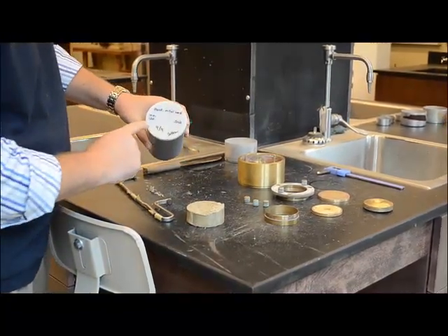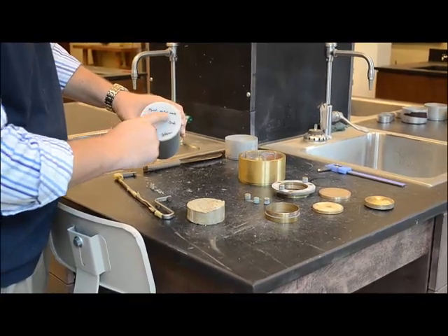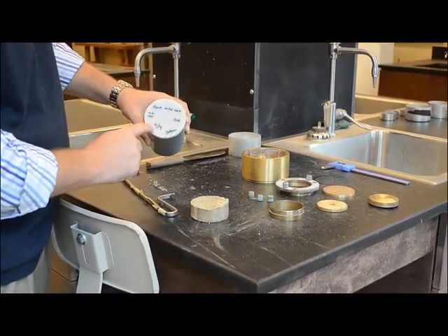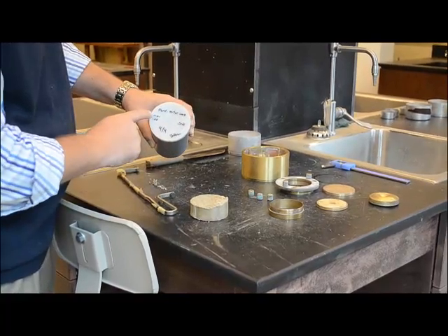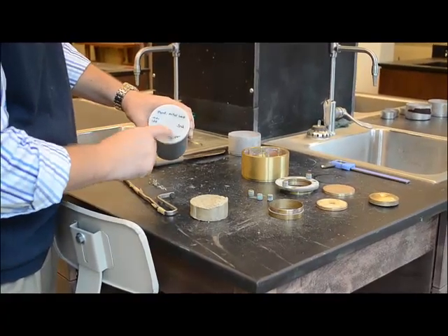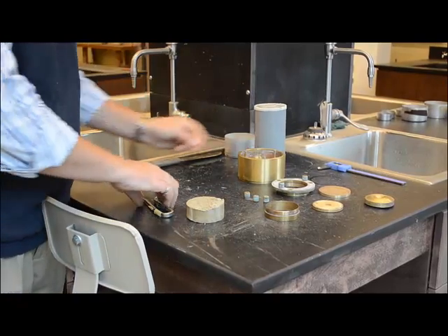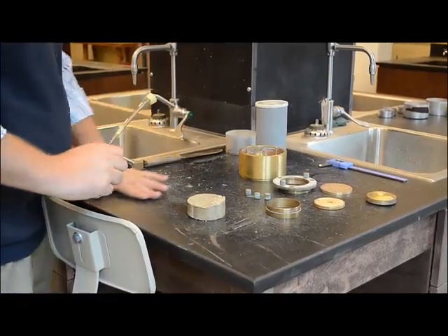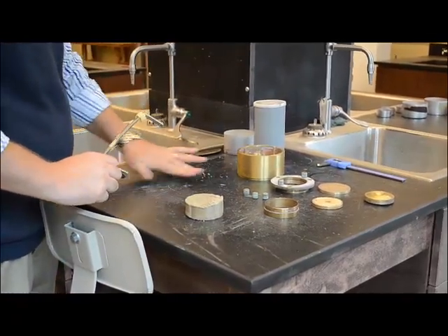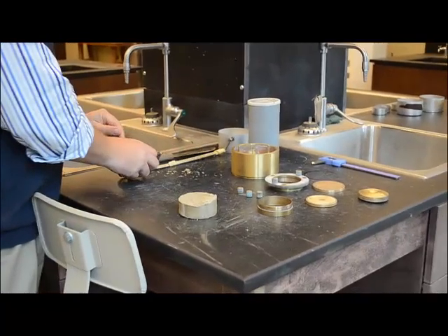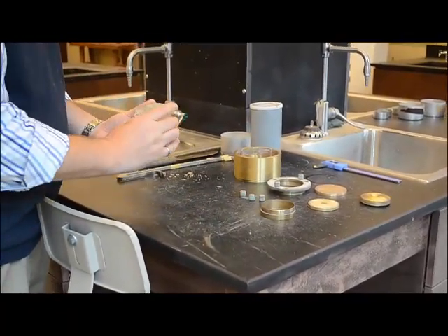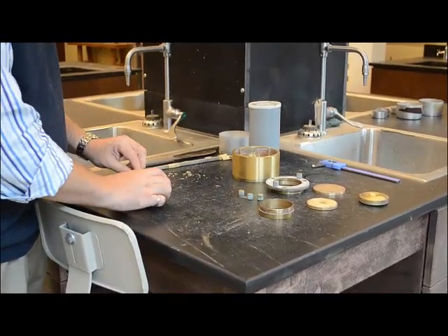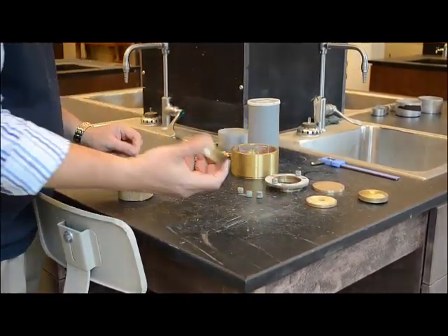The lid here gives a lot of information as far as the job number, the boring hole number. That is sample 4 of the Shelby tube, and that is the depth at which that was collected. I think this one's about 120 feet below the ground surface. And so that information is very important and relevant to understanding what sort of stresses should be applied to the soil sample during this experiment.